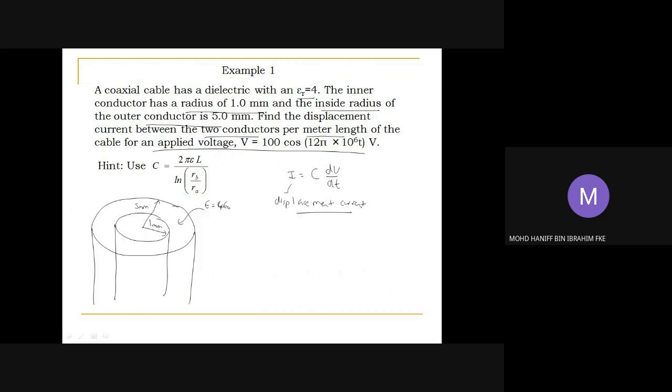In short, in your capacitor, the current that we have is the displacement current. The conduction current that we are going to have in your capacitor is the lossy current. It will not contribute to the capacitance, but it will contribute to heat, to the loss. We are going to learn this later when we learn about lossy dielectrics, but we agreed here that the current produced in your capacitance based on the equation C dV over dt is the displacement current.